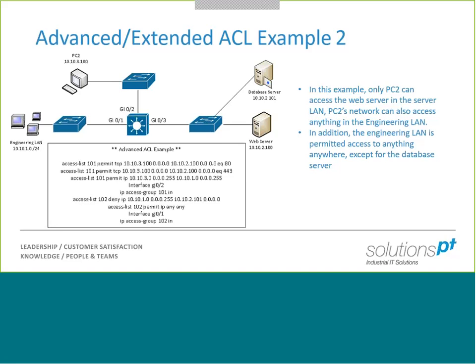Now, we come across situations on sites where the OT engineers don't own the layer 3 devices. Yes. So what are the implications there? By layer 3 devices, I'm implying that's where most of these ACLs will be set up. Generally speaking, they are, yeah. And there are a couple of ways around that. There are scenarios where we may want to use a transparent firewall, or even talk to the IT department. I mean, you probably won't get very far, but yeah.